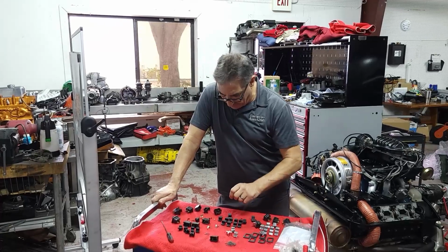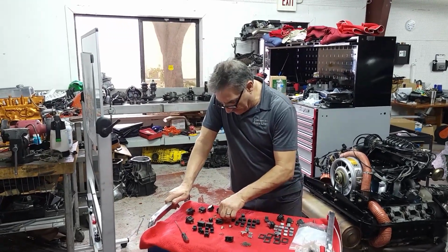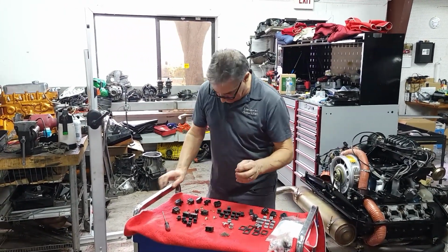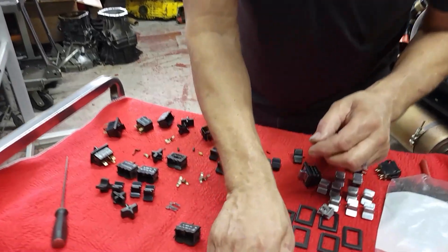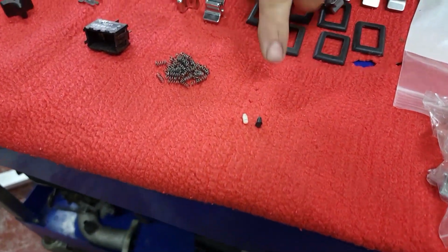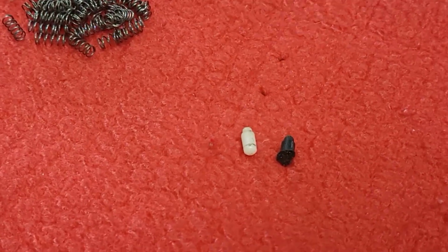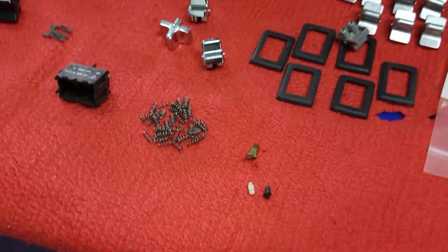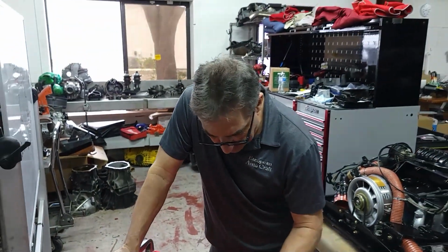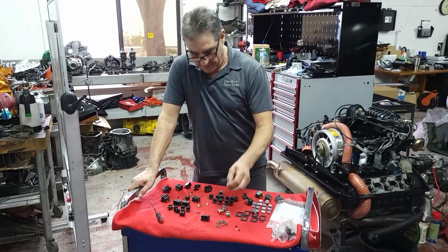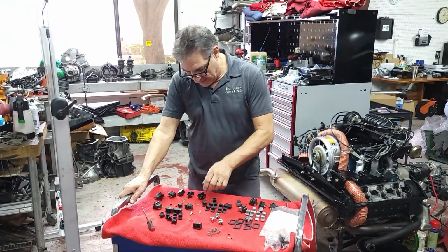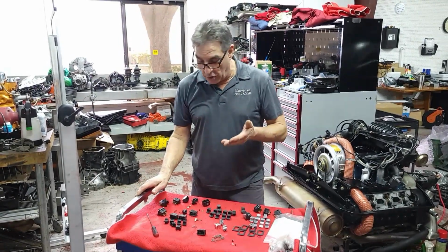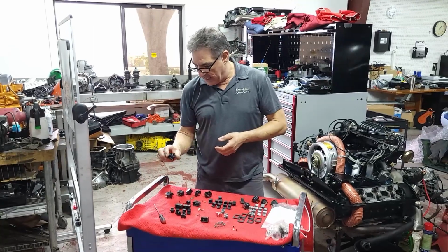The switches come apart fairly easy. Here's one of the things that happens when the window jams. I don't know if you can get a look at this. When the window jams, it overheats inside the switch and melts the little pin that pushes down on these. They're spring loaded. I had a bunch of springs made because the springs get overheated and they're not springy anymore. So I can rebuild these switches just as easy as replacing it, but it's a lot cheaper and you get a better quality product.